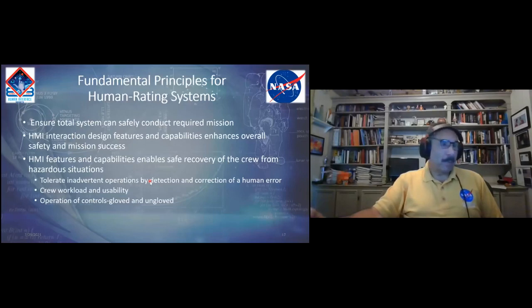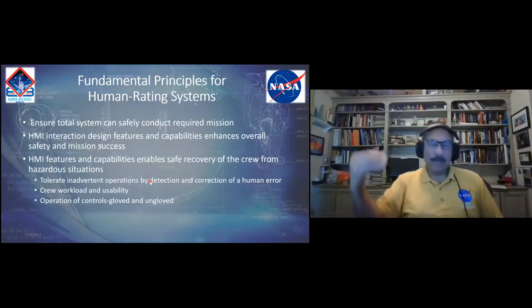This is the feedback. Okay. Oh, wait a minute. No, you cannot do it. You cannot press this button. You got to press this button first, and then this button. Or arming the system. Are you sure you want to activate this thruster? If so, then go ahead and press execute. So there's an arm and fire. It takes two stages in order to activate a critical function.